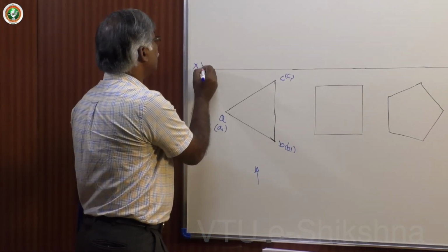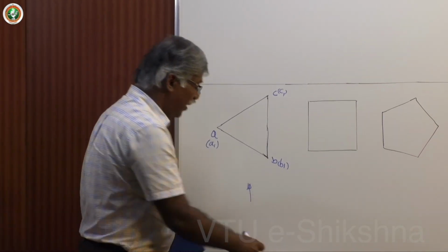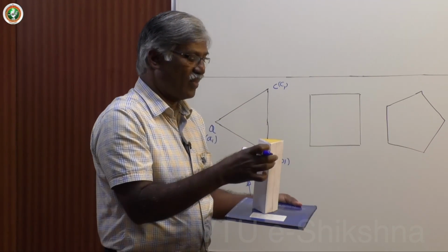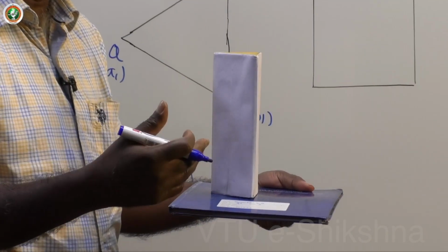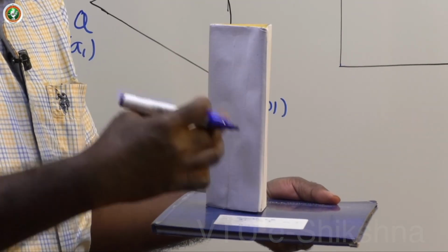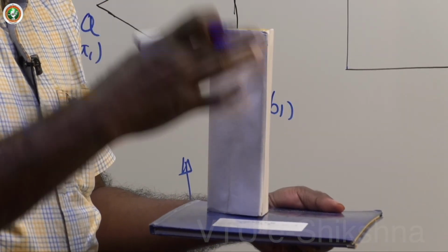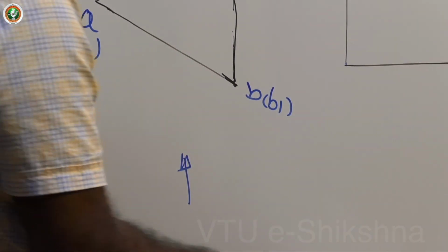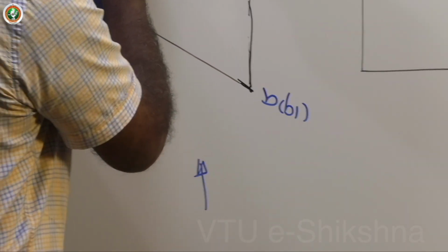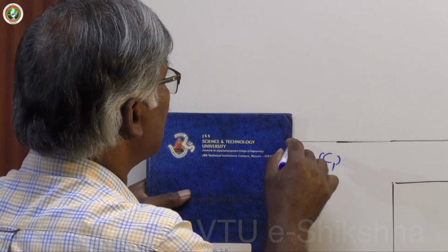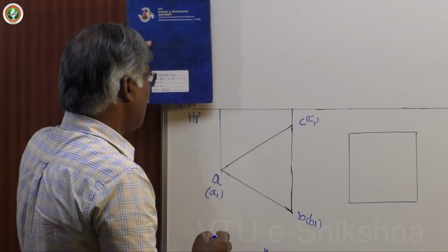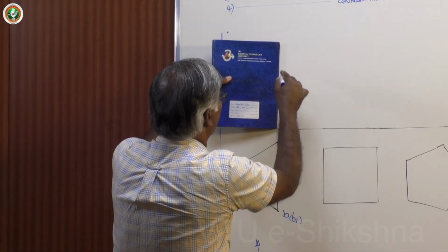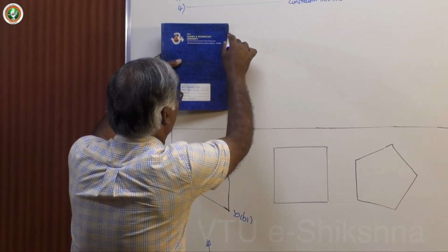Now the projection of the same in the front view is available. That is actually the apparent shape. In this case, it is the apparent shape of one of the lateral faces. Totally, this particular rectangle will be the front view. All other items coincide with the available one, that is the front surface. Now, how to get it? Just project this. Assume that I am projecting the base surface first on the HP, and assuming the given height, I will take this up to a particular height, that is the axis height or the height of the solid.